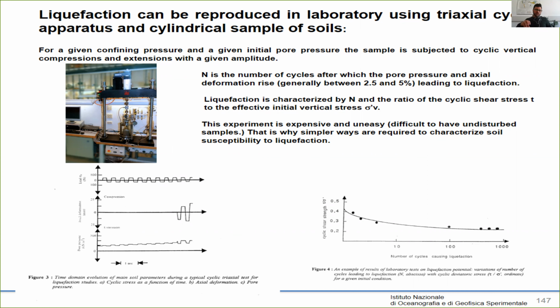So generally you see the apparatus here, you put the sample of soil, which is a small sample that should be undisturbed, and it is brought to a sort of confining pressure. And then for a certain pore pressure, you start having vertical compression and extension cycles of a certain amplitude. So you start compacting it and compacting it.